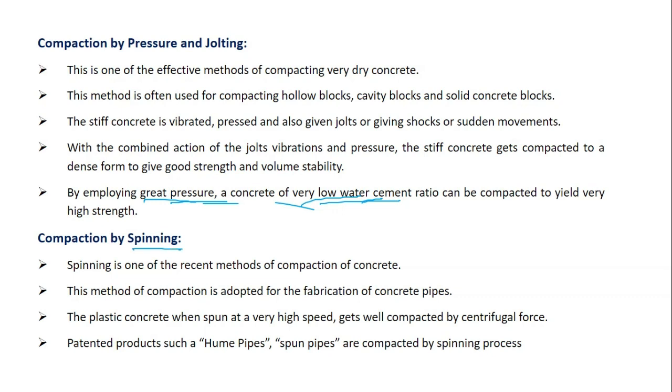And the fourth one is spinning. So in spinning, what we are going to do is rotate the member, such as in the case of fabrication of concrete pipes. Because of its rotation, because of the centrifugal force that develops on the member, it is going to expel all the air present inside the concrete.